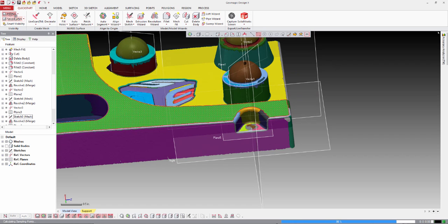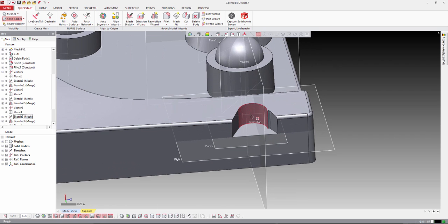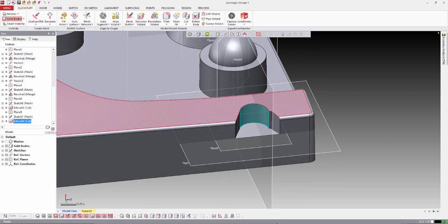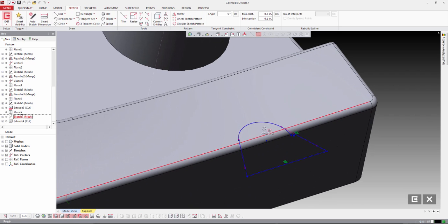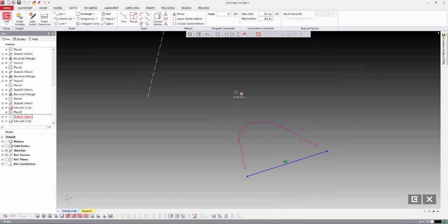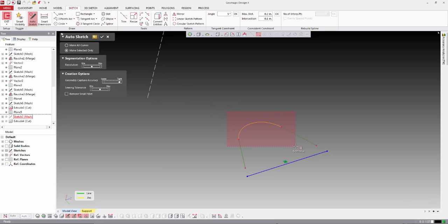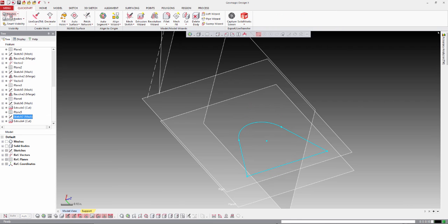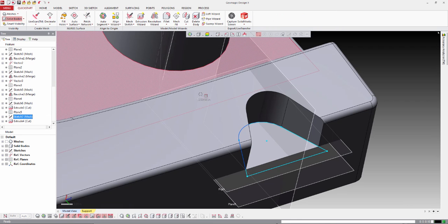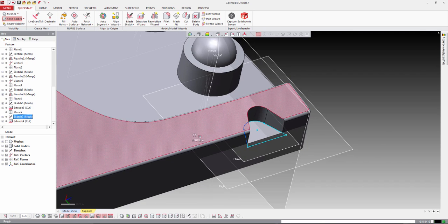Let's take a look at the solid that's created. That looks okay, but actually the sketch didn't quite form the way we wanted to. And one of the very nice things about Design X is that I can modify the sketch just by simply going into the sketch, checking it out, and modifying it. So what I'm going to do here is delete some of these edges. I'll hit the delete key and add some new lines, like so. And then close those lines with the coincident constraint, which automatically joins some of the lines. So by doing that, no surprise, the solid body's now updated. This is a parametric modeler, and we have that geometry exactly where we need it to be.